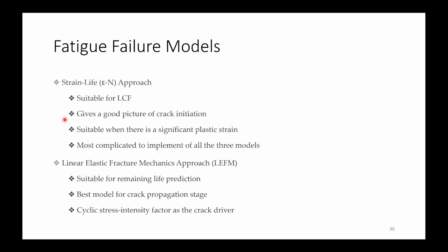It is the most complicated to implement of all three models. Third model is the linear elastic fracture mechanics approach. It is suitable for remaining life predictions, and it is the best model for the crack propagation stage, and the cyclic stress intensity factor is taken as the crack driver.